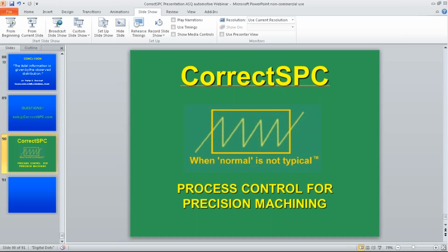That is adding variation. It doesn't need to be there. Plus, again, you don't want people to be your process. You want the machine to be the process. And the tool wear variation is going to occur anyway. Why add more variation on top of that? Just observe the variation that the machine is trying to do. Only adjust it when it's time for it to be adjusted. And that's what you want as far as a controlled process.